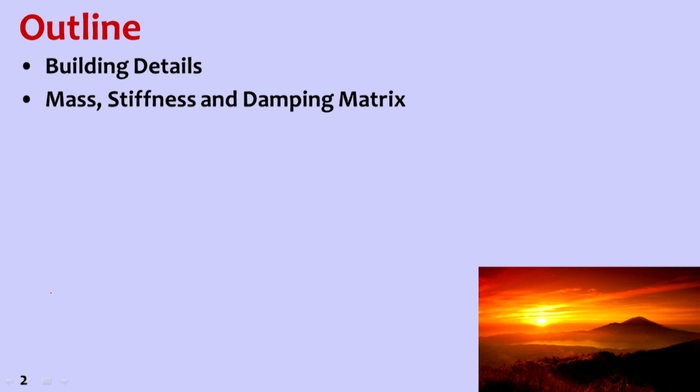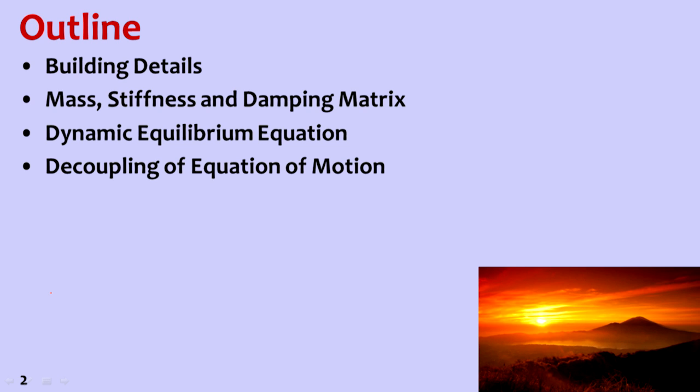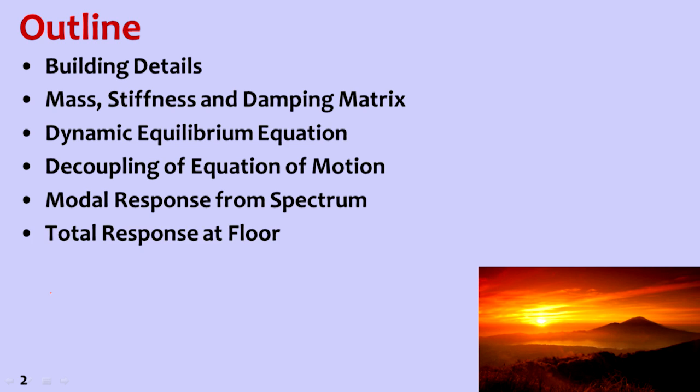Response spectrum analysis uses almost the same principles as time history analysis, but instead of finding the time history, we will find the maximum values of the response. So let us go to the outline of the class. First we will understand the building details and how we idealize the building into a lumped mass system. Then we find the mass, stiffness and damping matrices, then the dynamic equilibrium equation, then how to decouple these equations, and the modal response from the response spectrum. Then we find the total response at each floor, and then we will solve one example problem.